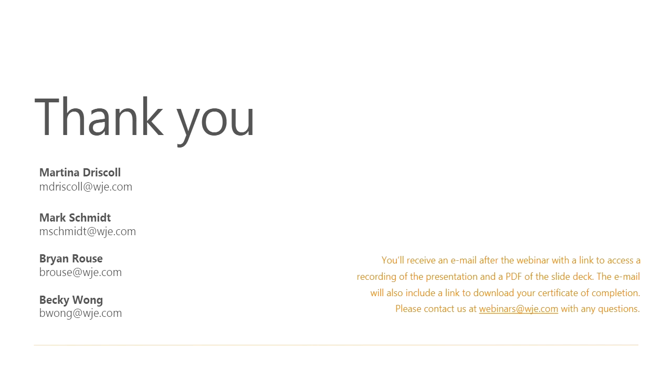So there's another question here, Martina, about vacuum insulated glass and whether it was considered for the MLK Junior Memorial Library. Yeah, that's a great question. We actually include a link to one of our other webinars on vacuum insulated glazing in our reference list. We didn't consider it for MLK. It does have the benefit of being thin, but it hasn't gotten there with optical clarity yet. You still have little standoffs that are required to keep the two panes of glass apart. There is a fledgling ASTM group on VIGs, though, if you're interested.